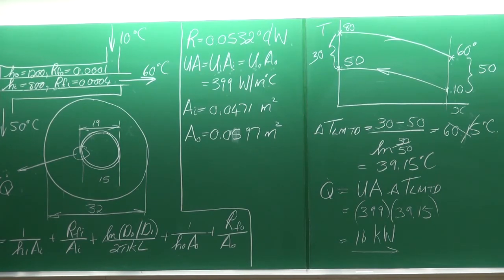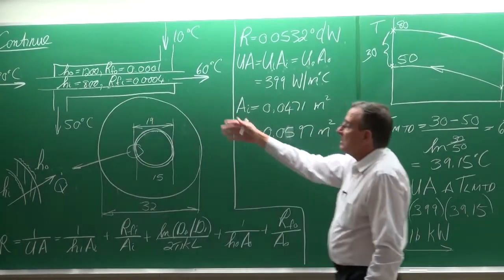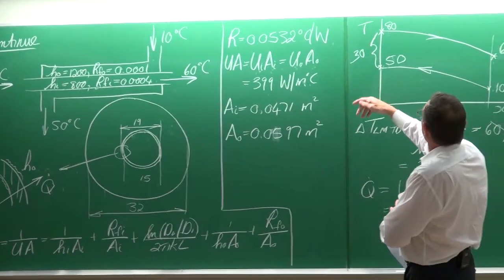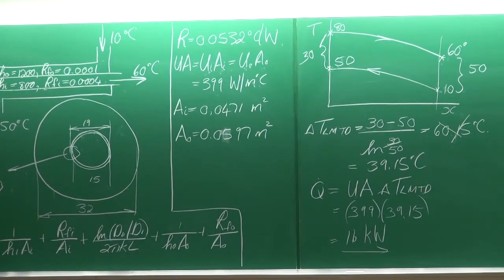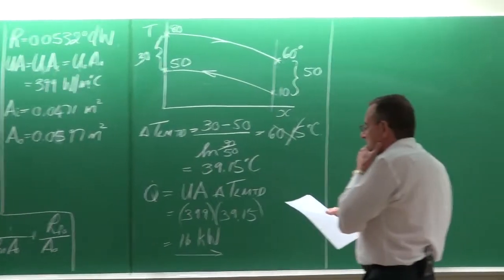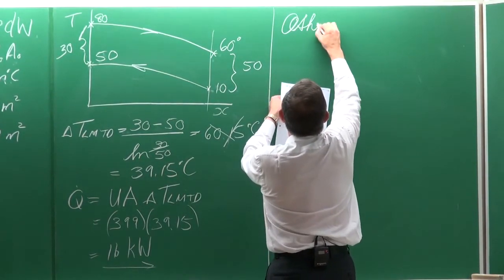Okay. Now, not all heat exchangers are the two types that we've started with, the counterflow or the parallel flow. The counterflow and the parallel flow are very easy. With the parallel flow one, the inlet temperature is going to be on this side and the outlet temperature is going to be on that side. However, now we can start having very complicated heat exchangers, cross-flow heat exchangers, etc. And the question is, what do we do with other types of heat exchangers?